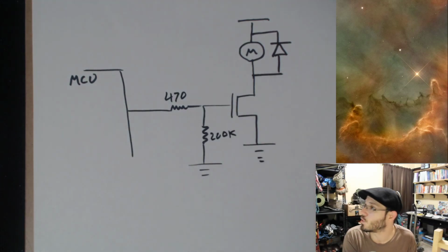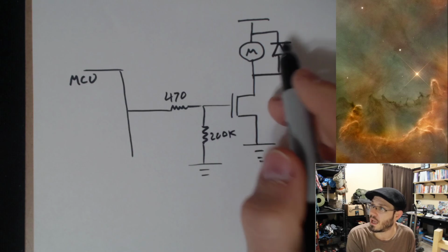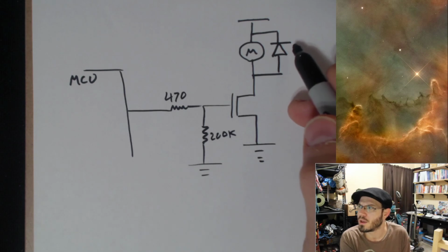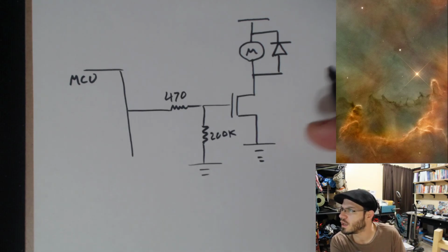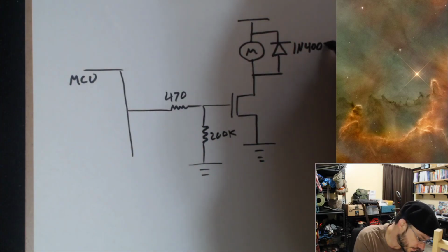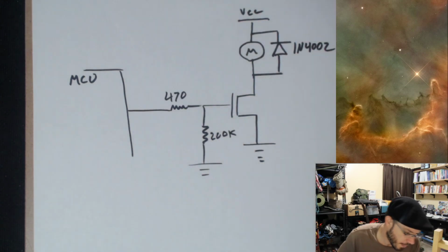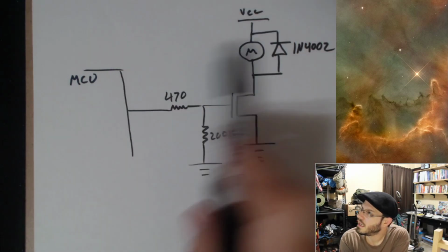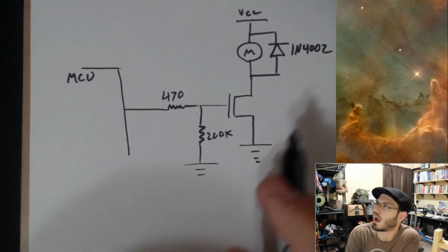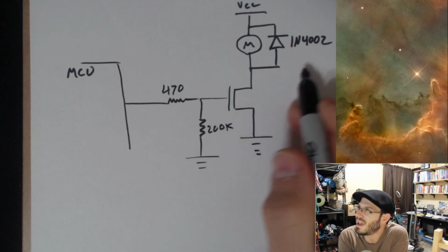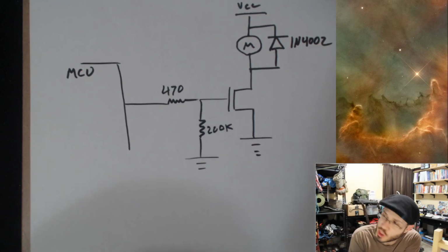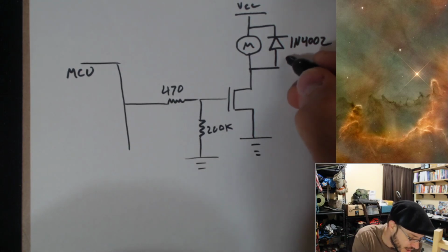Someone's about to ask what kind of a diode works well for this application. A 1N4001, 1N4002. Those silicon rectifier diodes can work pretty well as a flyback diode. So this is kind of the entire switching circuit to turn our motor on and off. Now you may also be asking, well, I said this was pretty good. Is there better? Yes. Schottky diodes work great in this application.